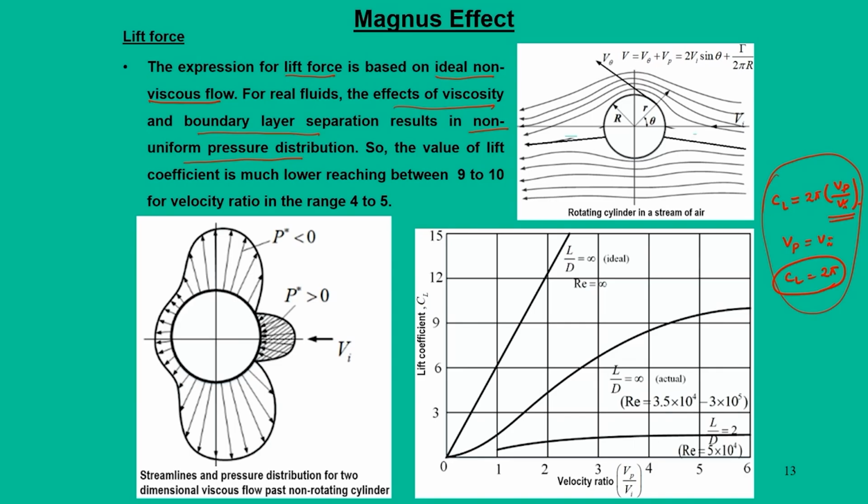For that reason, we define the Reynolds number, rho Vi d divided by mu. The Reynolds number is defined for the flow available in the free stream, which is the combined effect of the wind velocity, the diameter d through which you harness this flow, and mu, which stands for viscosity.